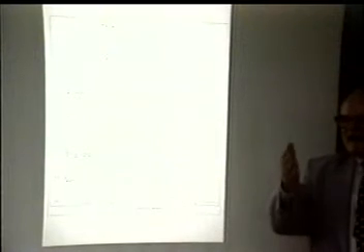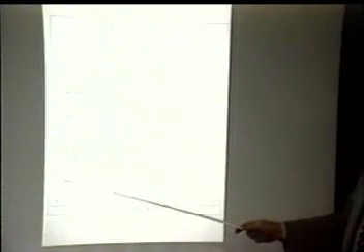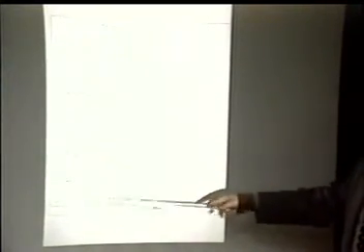If you get big differences, invariably, if you look at these shapes, let us say the effect here of the rigorous pre-buckling, or the buckling mode is completely different, okay? So I cannot give you a categoric answer that it is always good or always bad. You have to run it. And that is why we set up this deco the way it is, so that you can immediately look and see, oh, they are different. You go back, you look at these shapes and you see it yourself. Aha, that is the explanation. And if you then have such a situation, which is then good? The more rigorous one, right? Because that takes the effect into account.